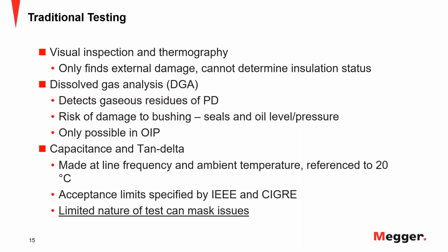We are not concerned about the ambient temperature. We're not concerned about the temperature of the transformer. We are concerned about the temperature of the internal insulation, under the upper envelope of the bushing. So this is critical, and you have to take into account that whichever way you decide to proceed with the temperature measurement, that has to be for everybody in your company. That has to be the plan for everyone else. So you're consistent with the data that you get, okay?